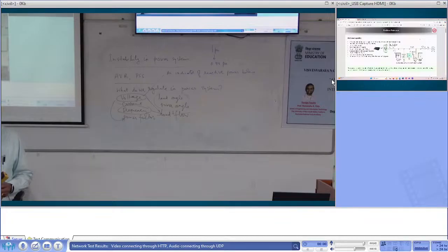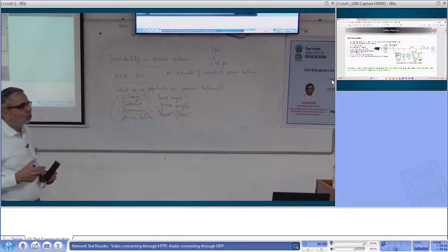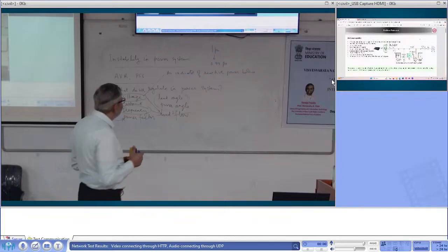Well, our assumption is that reactive power consumption is a function of squared voltage. Right? In the transmission lines, if you do the equations, you will see that the square of the voltage is involved in reactive power consumption across the transmission lines. So our assumption is that most of the transmission lines are inductive.